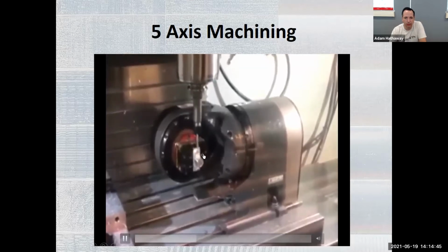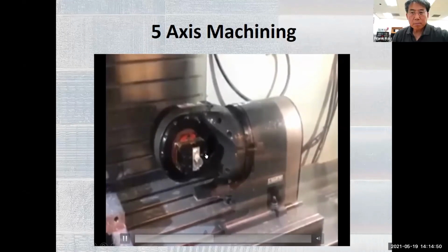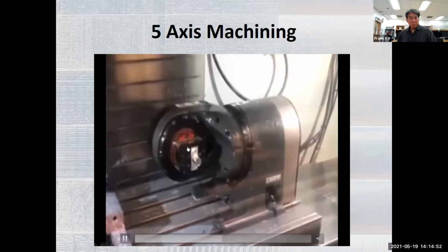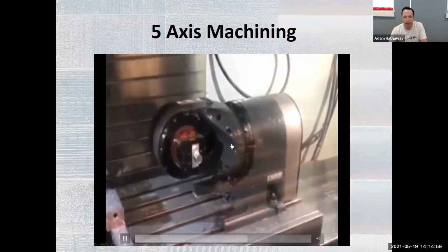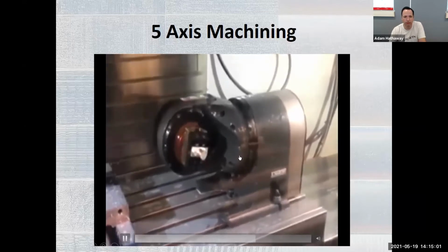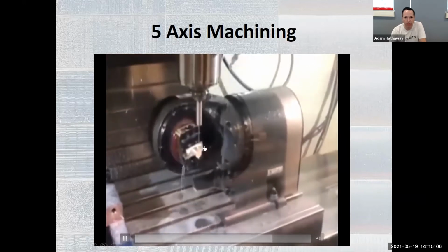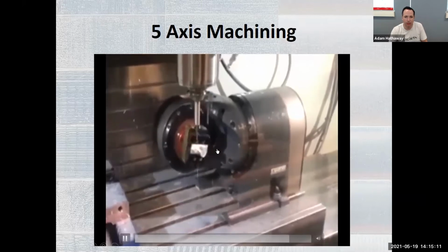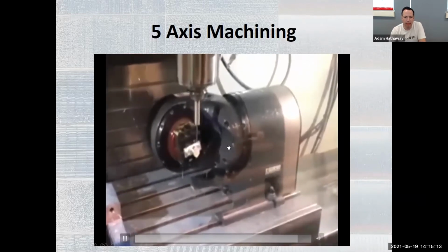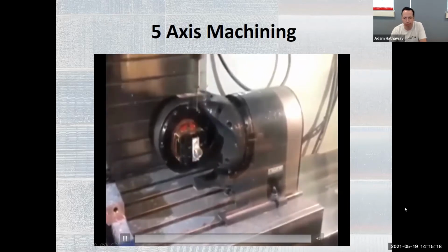So this is drilling holes around that flange. And normally this part would take several setups to make with modern machining technology. We here at Chabot make it with one setup where you just clamp it into this thing. And by precise control of this trunnion, we are able to machine that in one go. And that is the name of the game in machining, making precise parts and making them faster and faster. And that's part of the education we have here at Chabot.